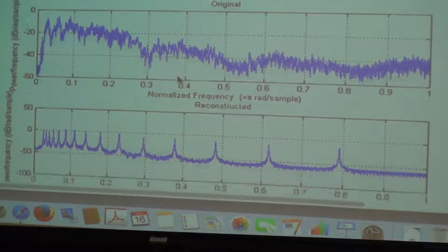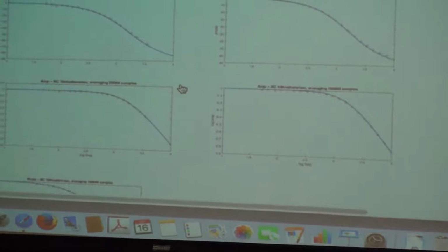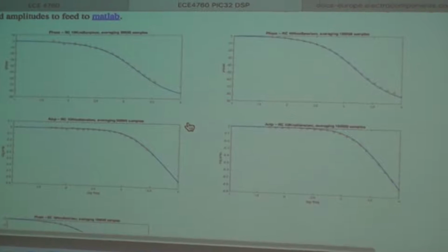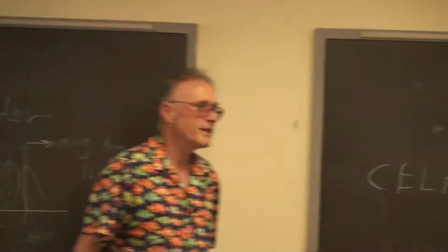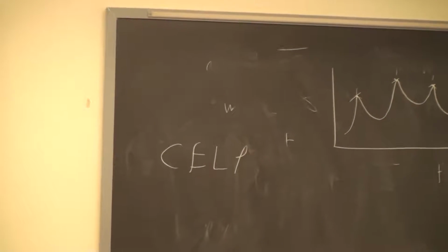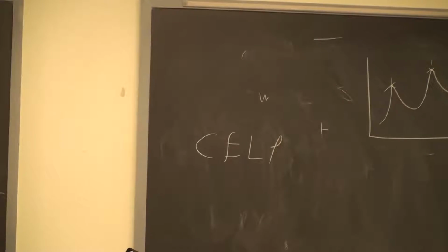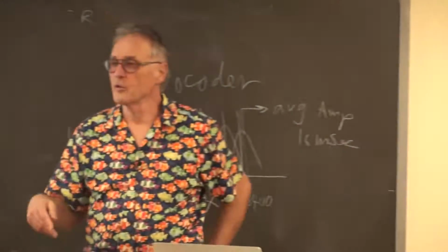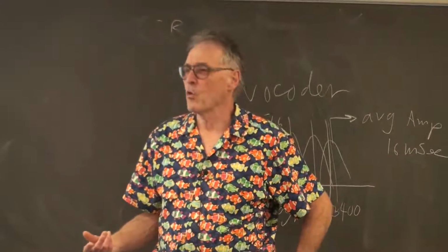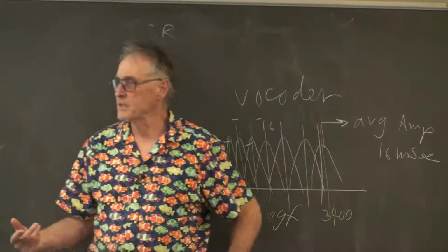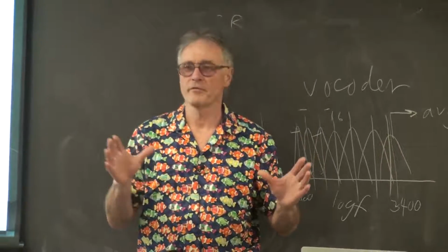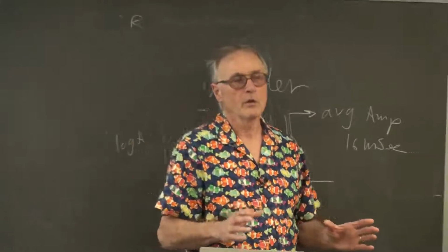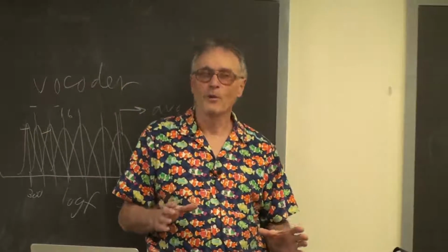I don't pretend this is optimal. If somebody wants to do linear predictive coding, code-excited linear prediction, CELP, as a final project, that'd be interesting. I think it's doable. Doing the playback is certainly doable. Doing the encoding requires inverting an n-by-n matrix every 16 milliseconds, where n is the number of poles in the filter. I think it's doable. I'm not sure.